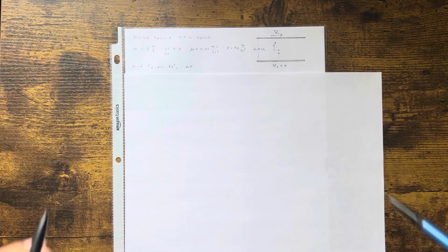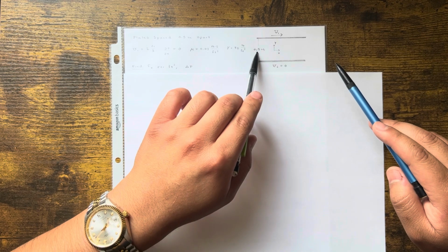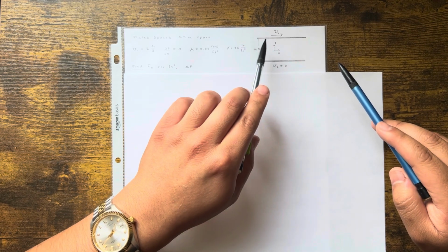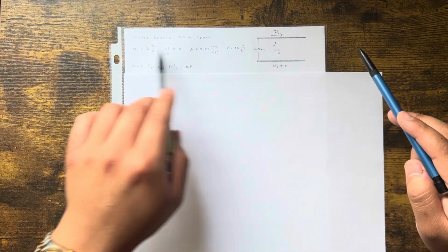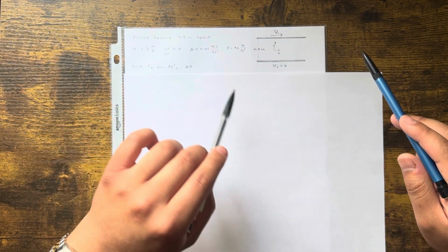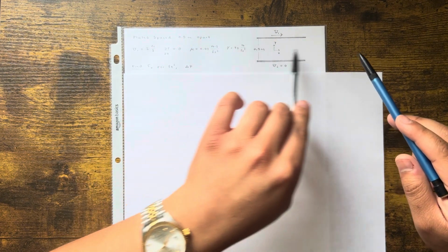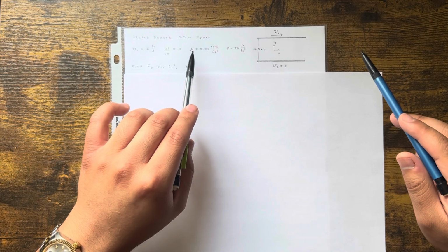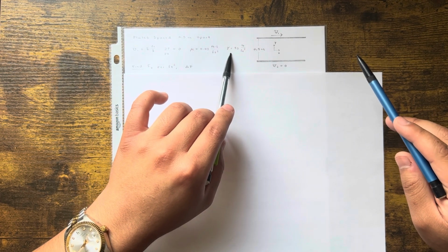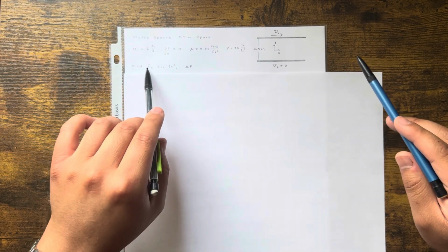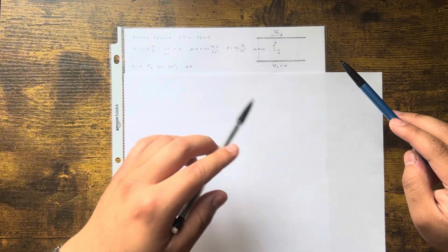All right, guys, so I just started off with the givens, right? The bottom plate is fixed. They're spaced 0.5 inches apart. U1 is moving to the right, I'm sorry, so it's a positive 2 feet per second. They tell you that there's no pressure gradient in the flow direction, which is the x direction, so that's 0. They give you dynamic viscosity, and then they also give you specific weight of the fluid. So they're telling us to find the force per feet squared, and then the change in pressure along the y direction.